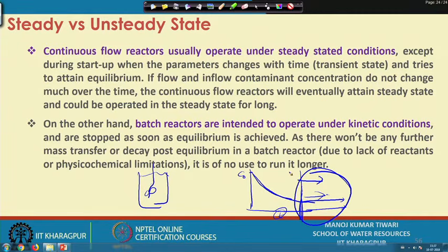but if I keep my system still on, it is just a waste of time and waste of resources, because whatsoever degradation or decomposition has to be there has taken place within this much of time. So, we want to run the batch reactors for this much time only, because running beyond this point is not of any advantage.